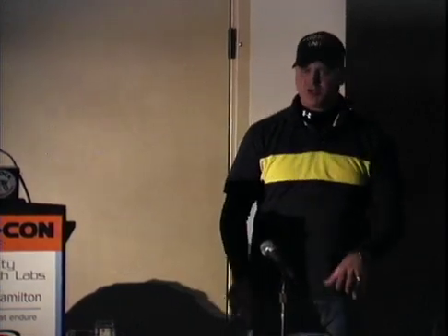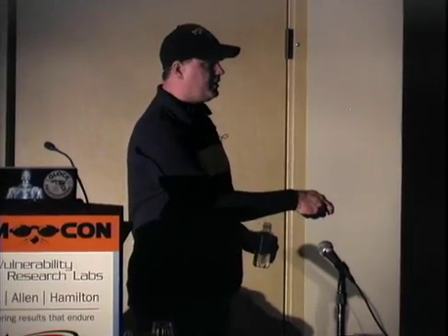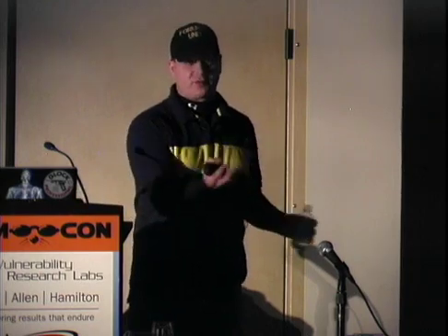You can almost fairly safely look at every drive except Western Digital's. Do not open Western Digital drives because the head assembly is attached to this nub through the lid, and when you do remove the lid, it causes an alignment problem in the Western Digital drive, and then you can no longer read. Even if it was an okay head, you wouldn't know that, because after you're through dealing with your other problems, you won't be able to realign this head.